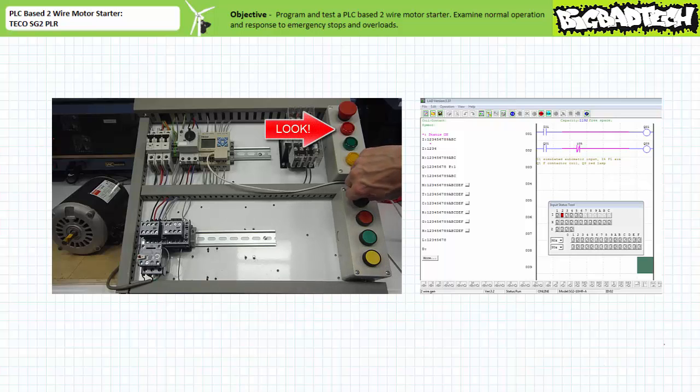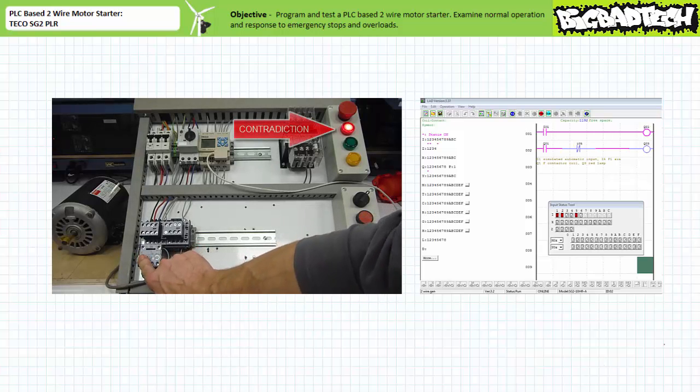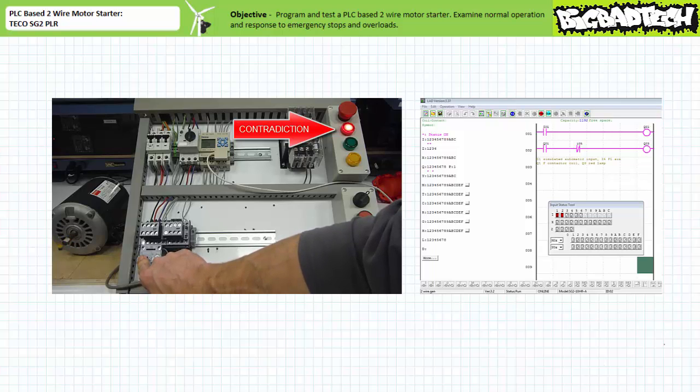As previously, when the selector switch on input 1 is closed, the F contactor coil is energized, the F primary contacts close, and the motor turns on. Again, you'll note the red pilot lamp briefly blinks on, indicating that there's a transitory period that output Q1 is being asserted and the F contactor hasn't fully closed.